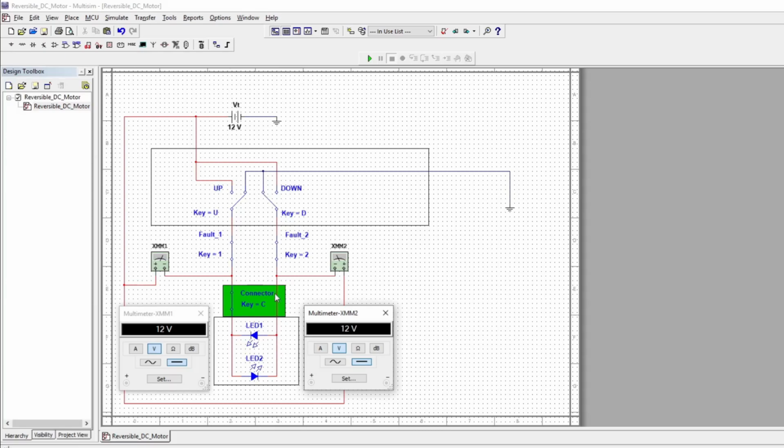And in this green area here, it's a connector, and I will simulate pulling off the connector. And we have our voltmeter here and another voltmeter here. Again, you'd only have one, you just switch it, but I'm putting both in here now. And what we have on both of these voltmeters, and this is going to be a common theme, again, power seats, power windows, power door locks, it's a common theme because they're all wired, almost all of them are wired in nearly an identical way.